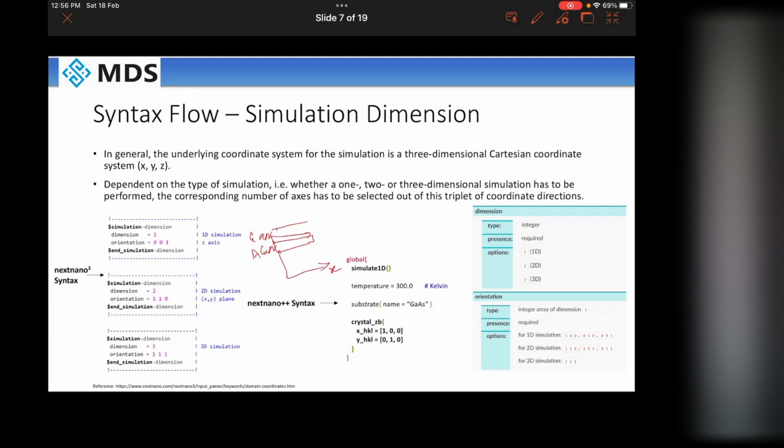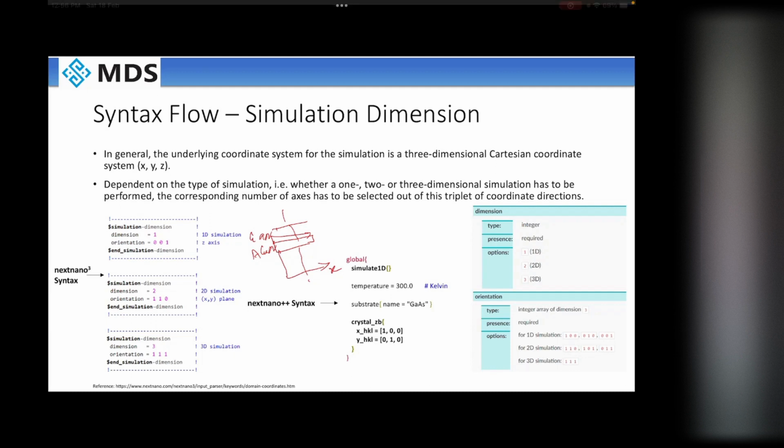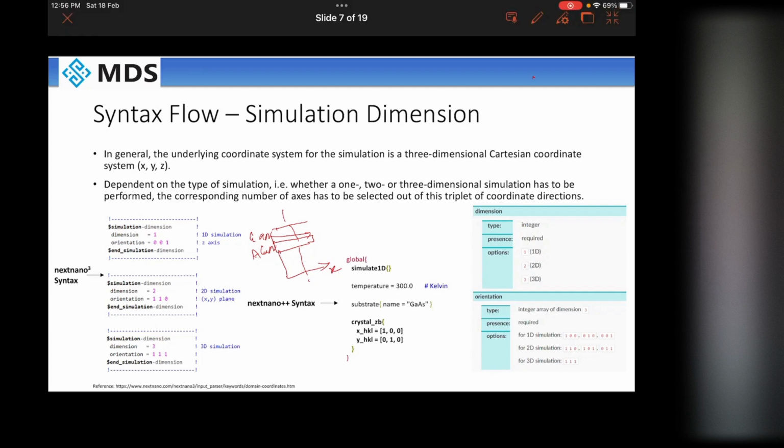You directly need to see how the band structure will look, what the barrier height is, and whether tunneling is happening or not. So you can simply take a cut line over here and start with that. Maybe later on you can do the 2D simulation, but it's good to start with 1D in that sense.